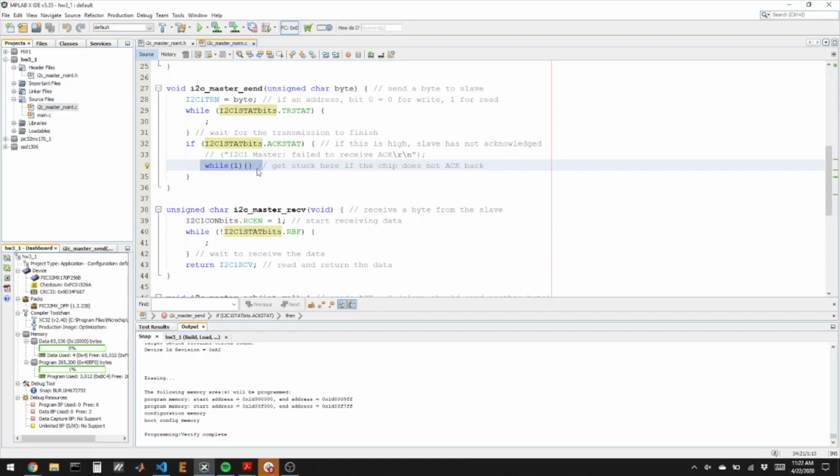your communication needs to be power reset if the PIC freezes. So in our PIC code, we'll always try to have some kind of blinking LED going on, so that if you notice that the LED is not blinking, probably you got stuck at this infinite while loop, and the PIC is no longer able to communicate with the device, due to the power reset.